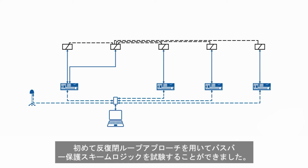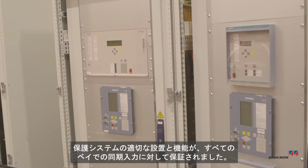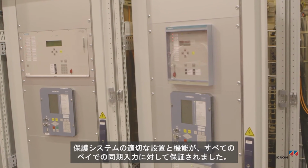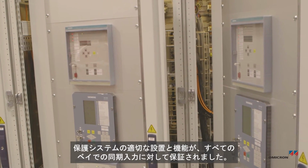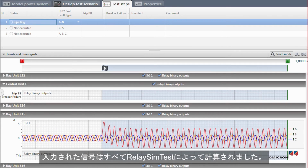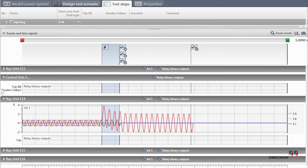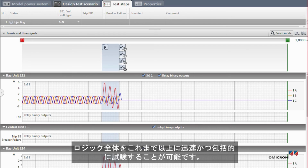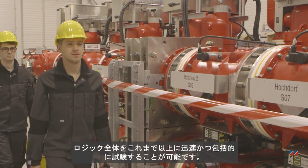For the first time, an iterative closed-loop approach could be used to test a bus bar protection scheme logic. Correct installation and proper function of the protection system was ensured through synchronized injection at all bays. All of the injected signals were calculated by RelaySimTest. The entire logic could be tested more quickly and comprehensively than ever before.